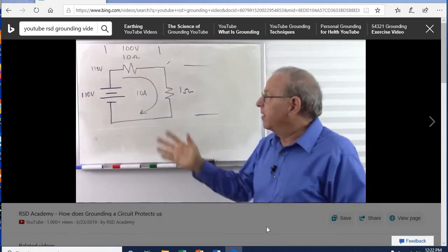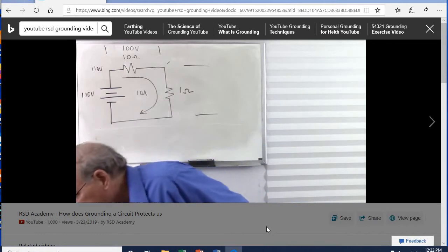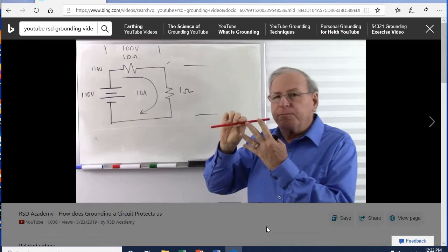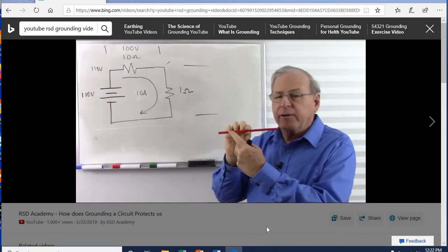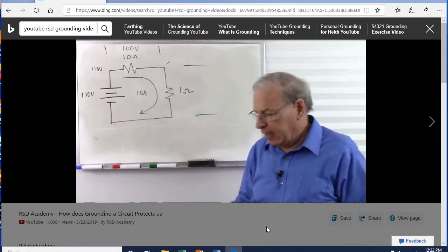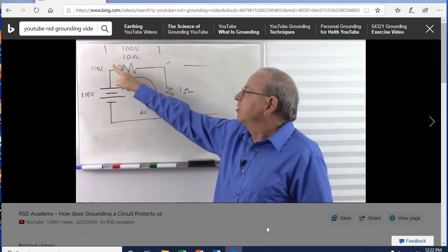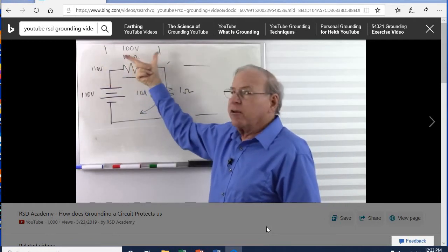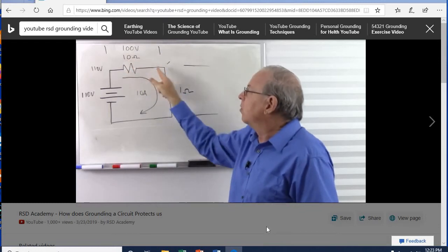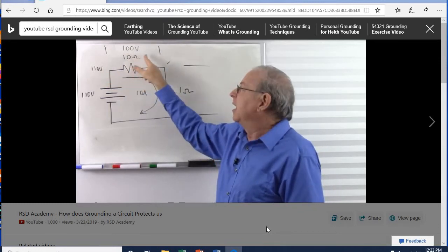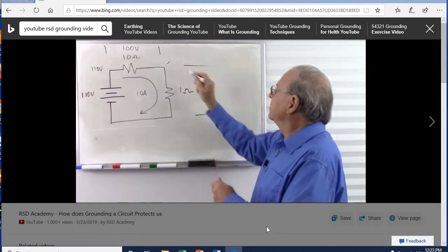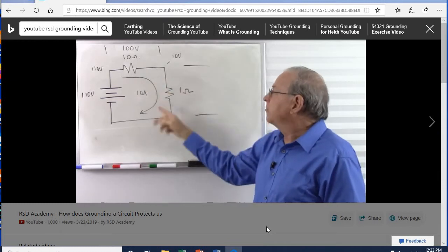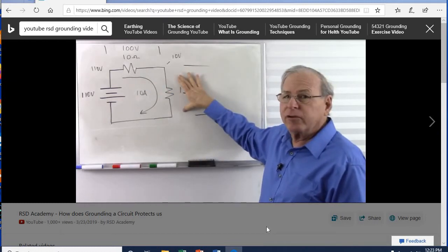So now I have a huge voltage differential. It's like I'm blowing really hard. Now I get a huge buildup in pressure here compared to the pressure here, and this pressure must be higher than that pressure. And once again, when we relate that to voltage, this voltage has to be higher than that voltage. This voltage is locked in at 110, so if I have a greater voltage here, that means I'm losing more. So I started with 110, I lost 100. What's left over? 10 volts. So now, with this 10 amps, I only have 10 volts left across this 1 ohm resistor.